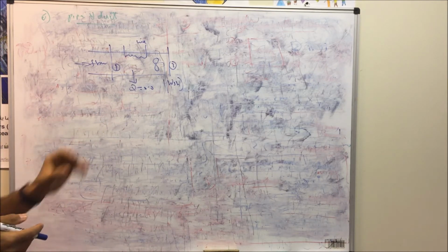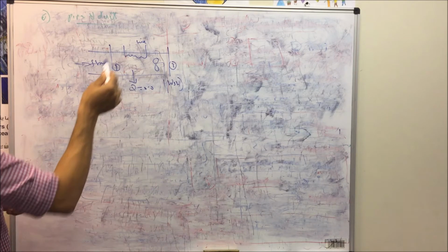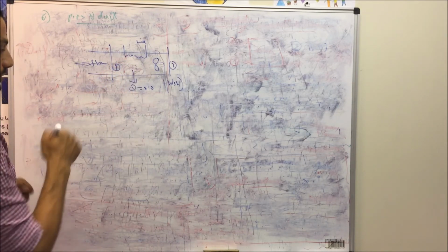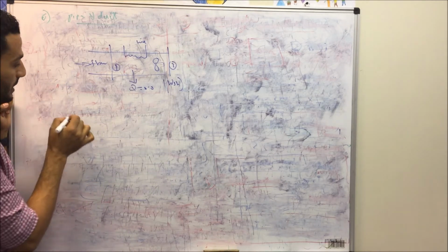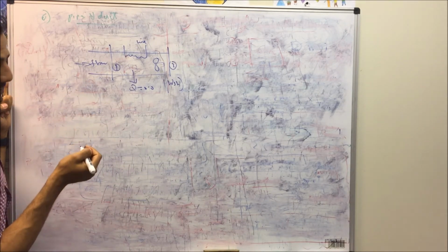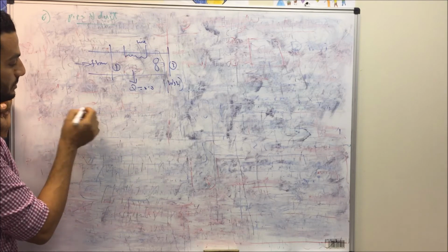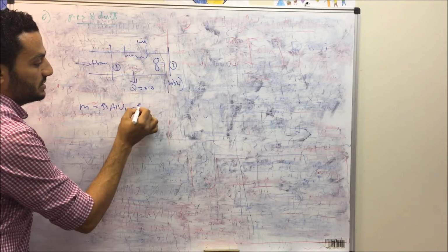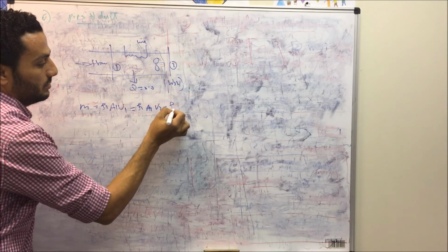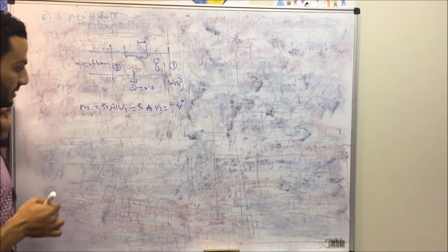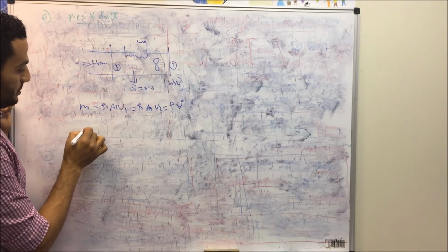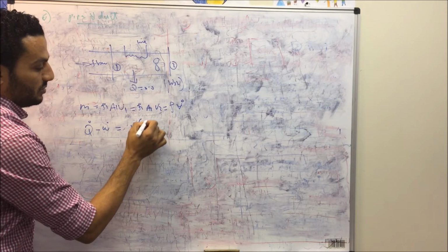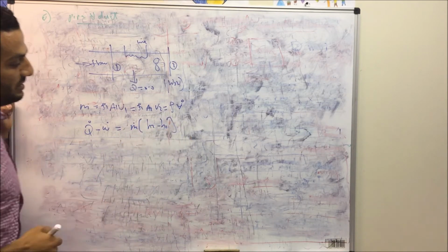So we'll consider the general flow in pipe and duct. We may have any kind of heat transfer or adiabatic, or we may have any kind of work. So we'll consider the case as given to you. We can apply the steady flow open system general energy equation and also the mass equation. So the mass equation will be m dot equals rho 1 A1 V1, the same as rho 2 A2 V2, equal to density multiplied by volumetric flow rate.